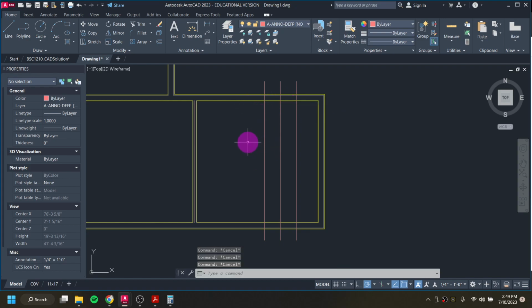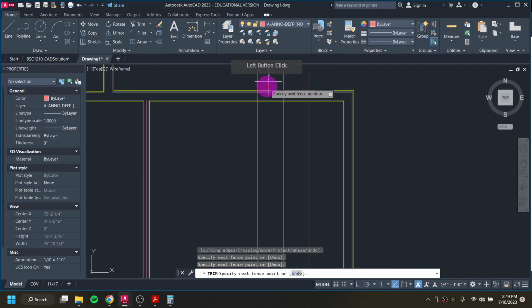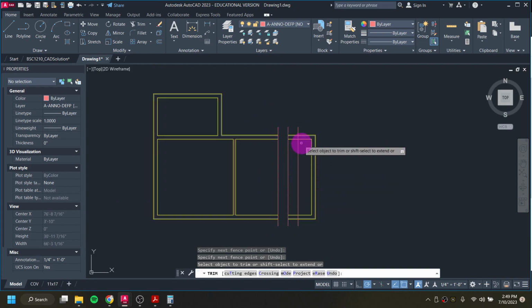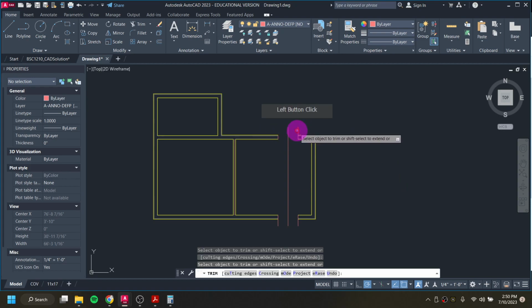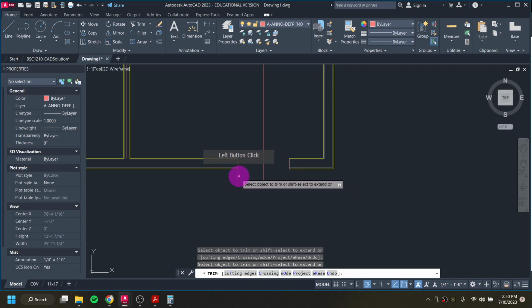And then I'm going to go into the trim tool. So that's keyboard shortcut TR, enter. And all I'm going to do is, for me, I'm going to click up in this abyss and just bring it straight down. So I get all of that in one go. Same thing this way. And then I'll get rid of these edges. I'll get rid of this up here. And I'll get rid of these down here. I am going to keep that middle line because I'll switch it into that grid line. So this way I can just kind of borrow it.